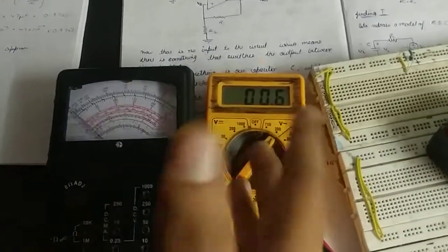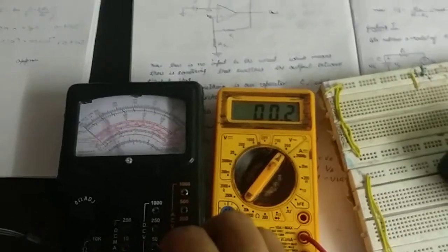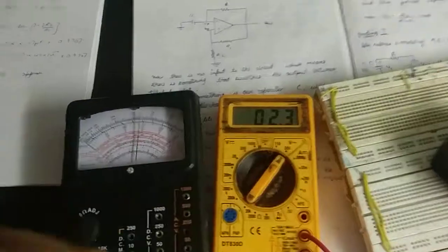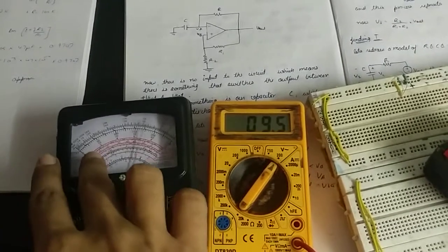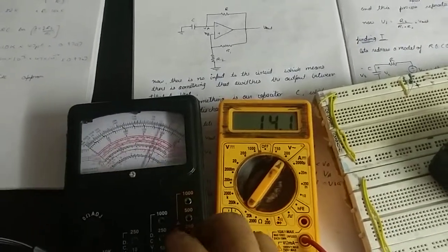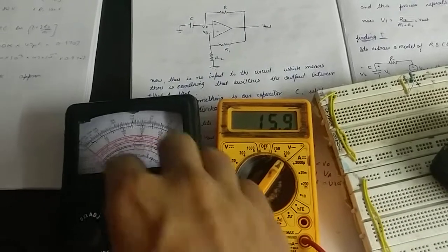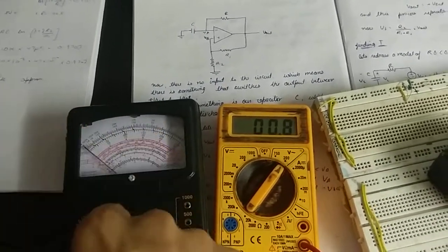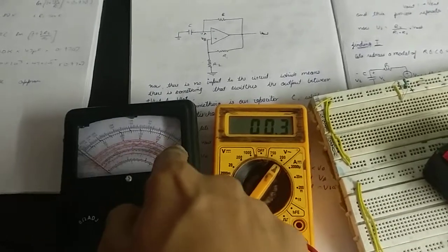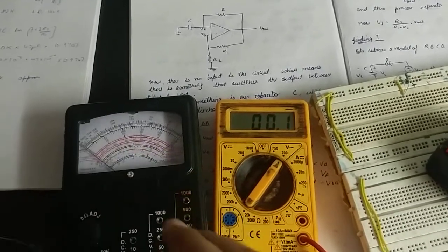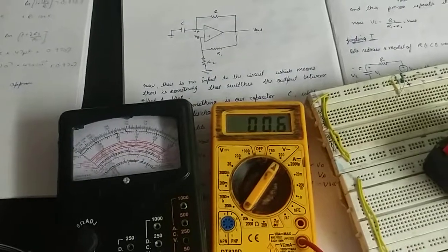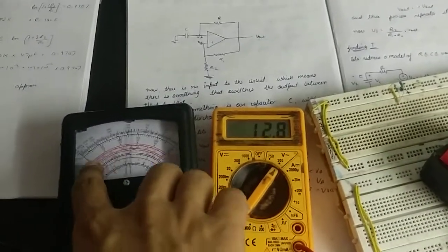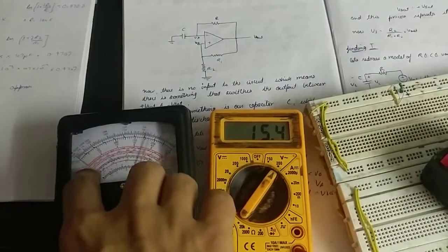You may be asking, what happens if I measure DC voltage out of it? Let's connect it with DC voltage, DC 10 volt. As you can see, it is holding a position near zero, because the DC meter does not show negative. That's why it is showing zero wherever it is negative, and where it is positive it is going towards 9 volt, because our voltage actually moves from -9 to +9. So it's only showing the +9 signal, and the -9 is not able to be displayed here.